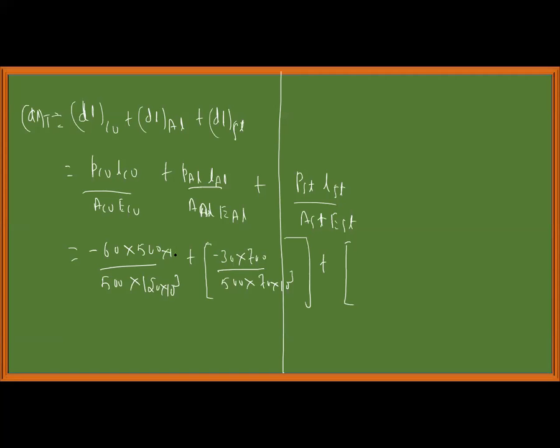I should include 10 power 3: 50 into 10 power 3 into length of steel, it's 300, by area of steel, remains the same, 500, into Young's modulus of steel, it's 200 GPa, 200 into 10 power 3. Cancel 10 power 3 and tell me the answer. Total deformation is equal to, in mm, find that. You can take out the common factor in the denominator.